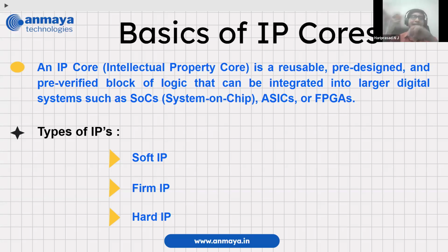One best example is that nowadays we get something called RFSoC from Xilinx or AMD. That particular IC is designed for RF applications or 5G applications, wireless communication. So they have a lot of hard IPs in terms of DPD, digital up converter DUC, DDC, up converters, and I think they have turbo decoders and encoders. These are all hard IPs. Basically, that chip is specialized for the application. So whenever you have more hard IPs, it will become like an ASIC itself.